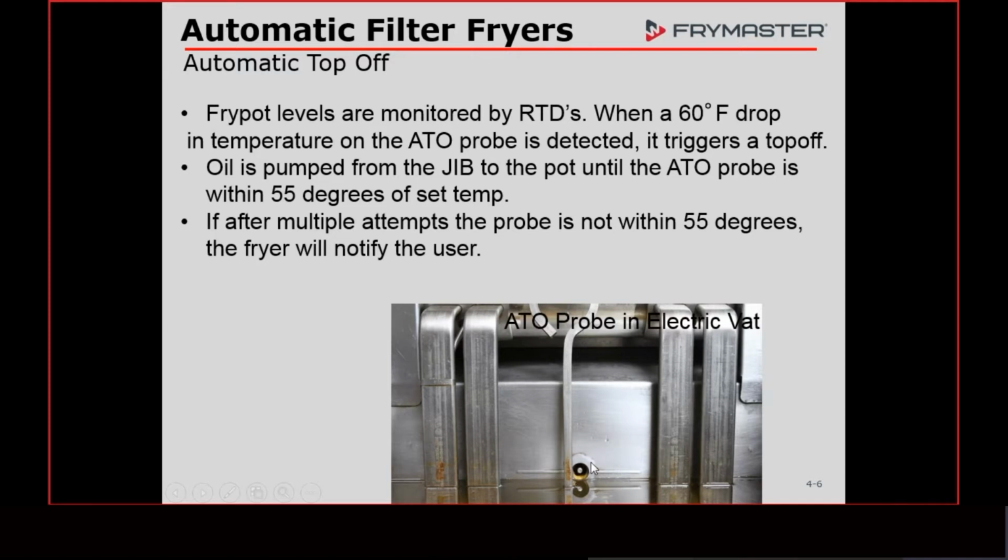So whenever this probe senses a 60-degree drop in temperature compared to the temperature probe, that's when the ATO system engages, okay? And then once it raises 5 degrees, or is within 55 degrees of the temperature probe, that's when it stops. Yeah, that's how the ATO system works in a nutshell.